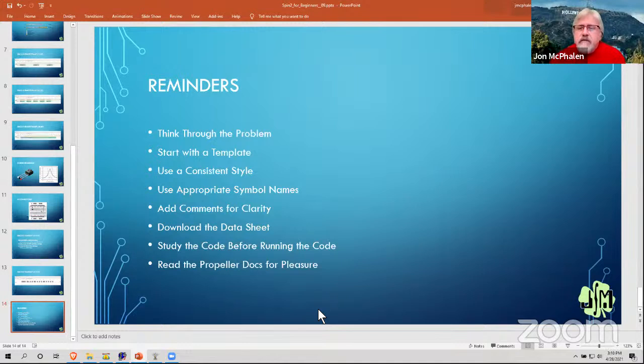the S-Bus stuff. In the world of animatronics, they use those remote controls to puppeteer animatronics. Back in the old days, we used to write code that would look at the pulses out of an RC receiver and measure them, and then provide that to the program to do something with. With S-Bus, it's nice because we just have a serial data stream that we have to decode. So we have one input to the Propeller and we can get all of these values.